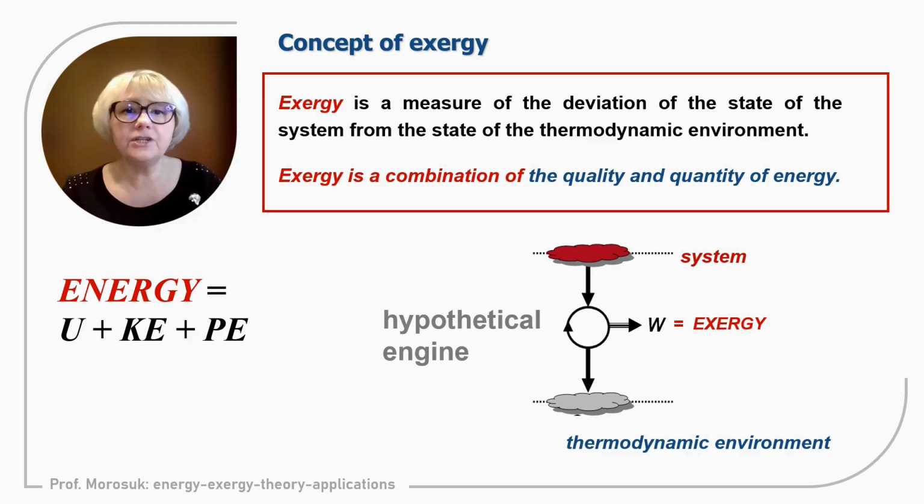And also exergy, it is the measure of the deviation of the state of the system that we would like to calculate exergy from the state of thermodynamic environment. So again, I would like to remind you that within exergy, we will continuously refer to thermodynamic environment, but not natural environment. Okay, if we discuss about energy, please remember energy. In thermodynamics, it is the sum of internal energy, kinetic energy, and potential energy.